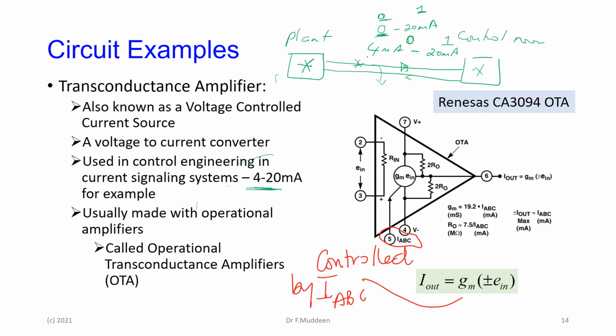So to avoid that, they set the lower limit, and this is a standard that is set internationally. They set the lower limit as 4 and the higher one as 20. Historically, there are some other reasons why the range came in, but the lower limit came in so that if instead of 4 you're getting 0, you know there's something wrong with the wire, right? So it's like a self-testing wire. You're supposed to have a minimum of 4 and a maximum of 20. If you're getting outside of those ranges, it's telling you something else is happening around the place.